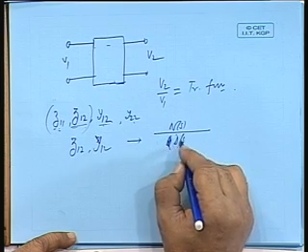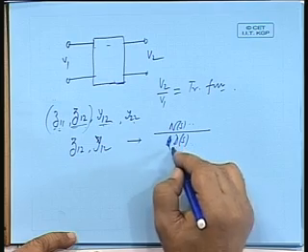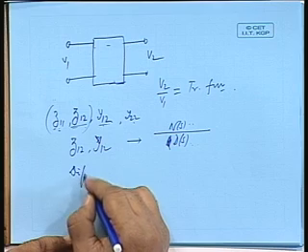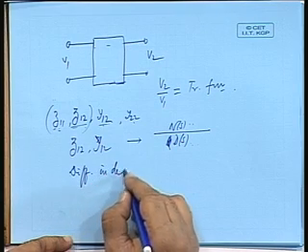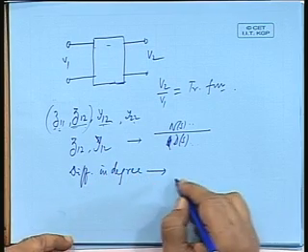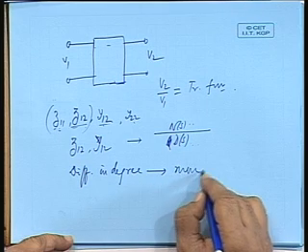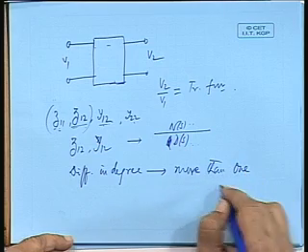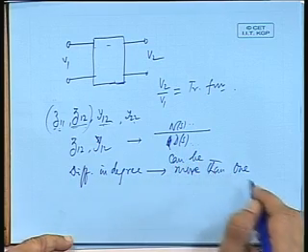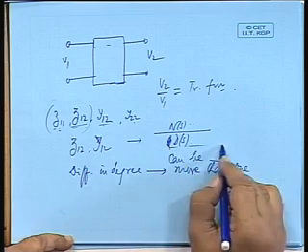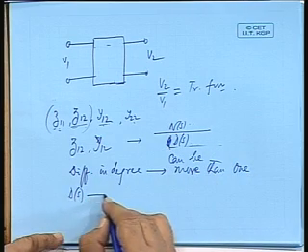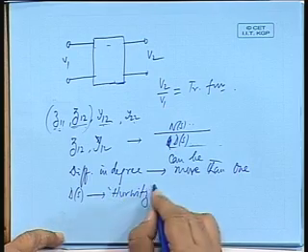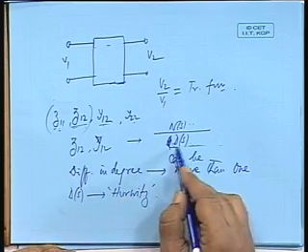And so, for transfer function also, we will find the numerator and the denominator polynomials, Ns by Ds. They need not have all the properties that were listed in the driving point synthesis, that is, the difference in degree can be more than 1, may or may not be, but Ds must be a Hurwitz polynomial, roots must be always in the left half plane. So, Ds must be Hurwitz.